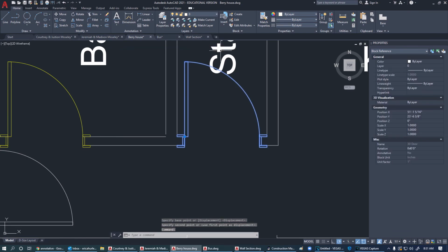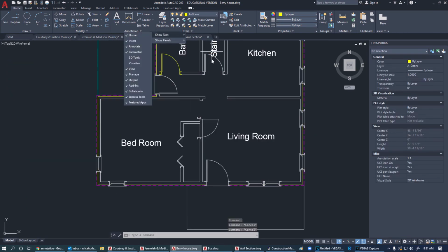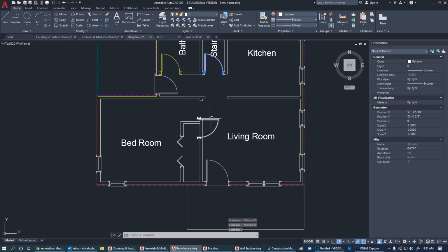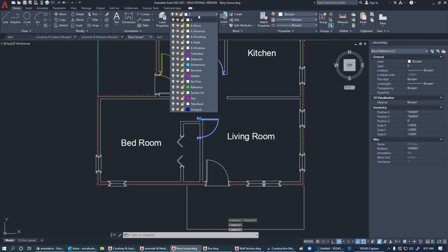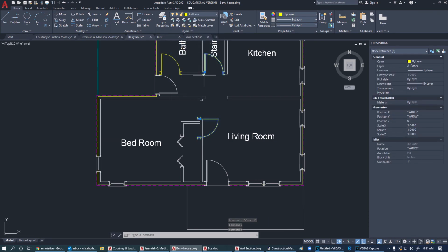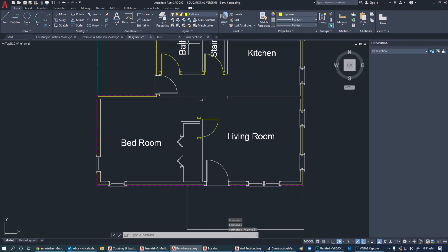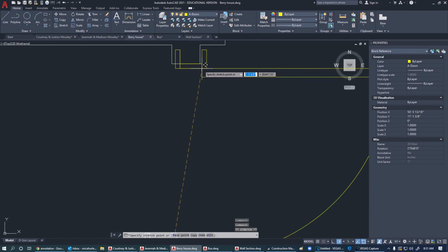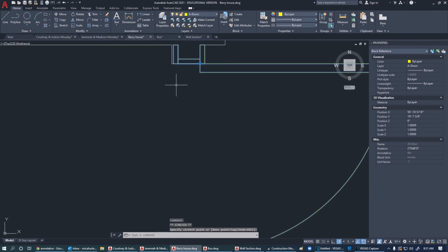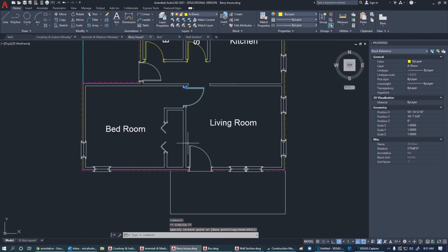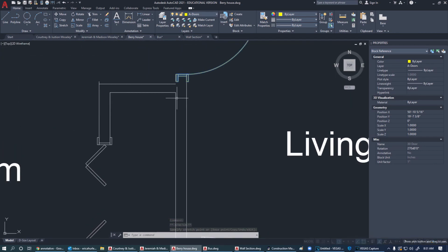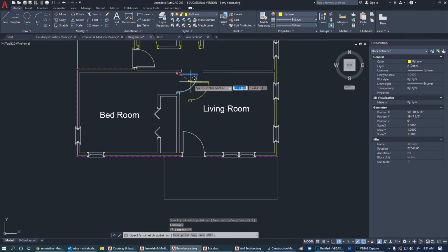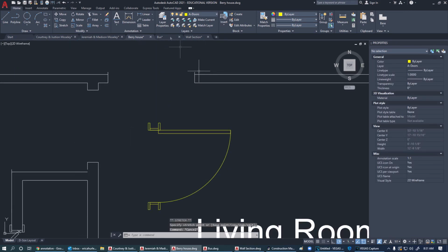And also, it's on the wrong layer. If I drew a new one, it would be on the right layer, so I'm going to go back here and highlight these doors here, and I'm going to put those on the door layer. So all I did was highlight it and then just change the layer there. So this one, again, I'm going to move this back where it should go. I haven't changed this. I guess I need to do that first. So let's just move that door.